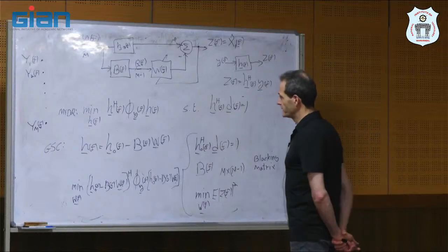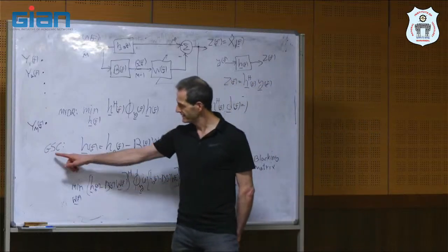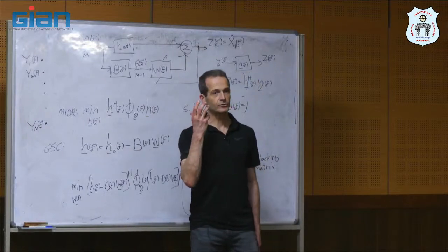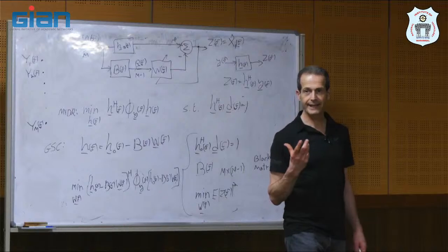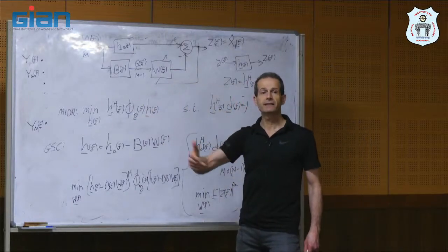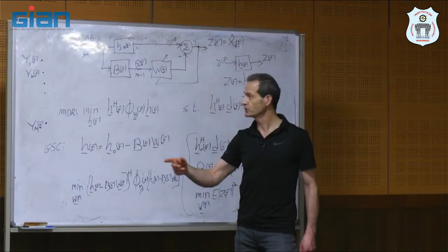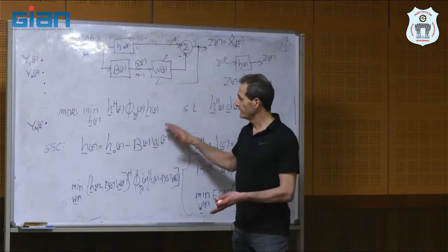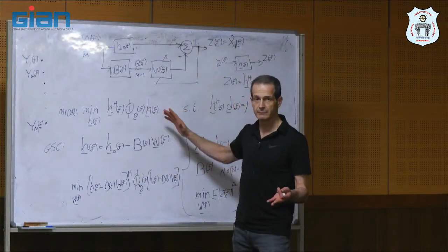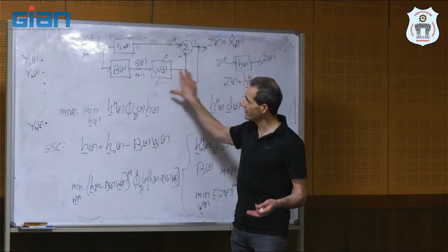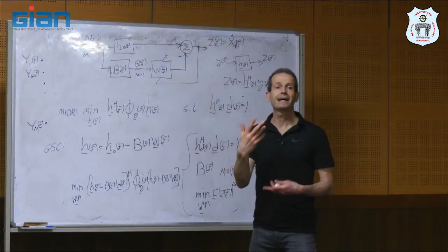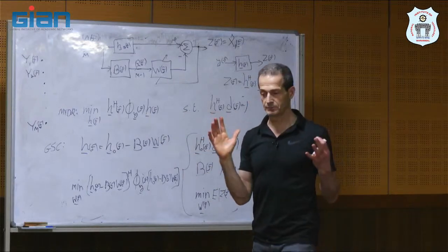Okay, so we see that the GSC gives us a very nice, attractive way to obtain the MVDR solution as a real-time adaptive solution, an adaptation of this filter. If we use an offline solution, in theory it's the same, but the structure gives us a way to do an adaptive solution, which is beautiful.